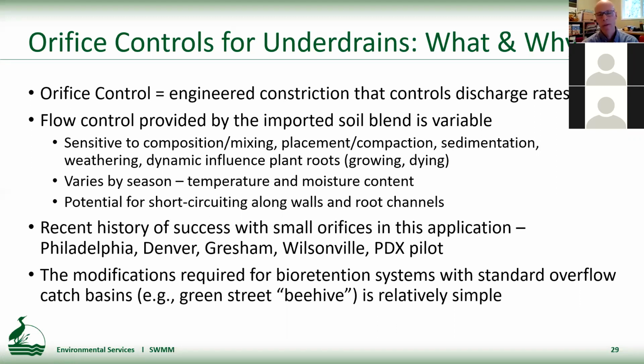And why are we doing that? I think it's common knowledge these days. We aren't the only ones to conclude, over the course of many years of monitoring, that the blended soil produces mixed results when it comes to providing flow control. The blended soil material is sensitive to a lot of things: the composition and mixing, how the material is placed, the moisture content, when and how it's placed, is it conveyed into place, sedimentation over time, and the weathering of the material.